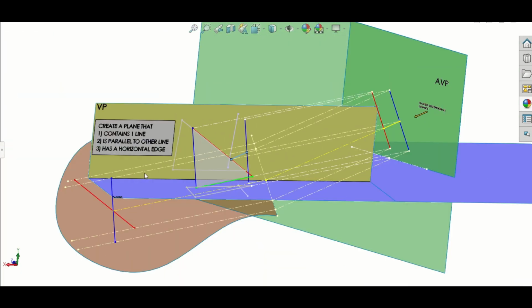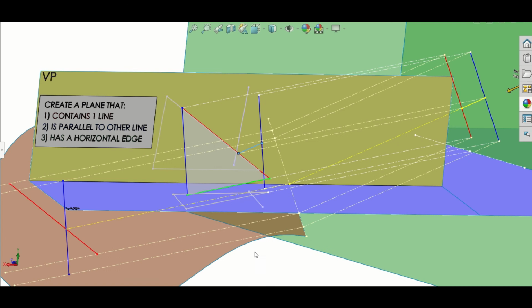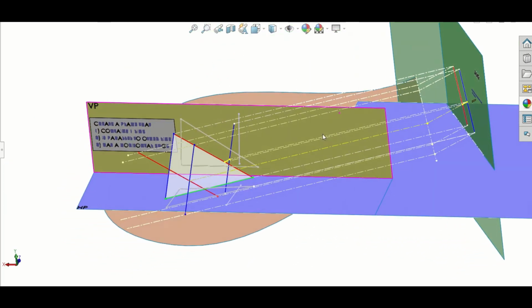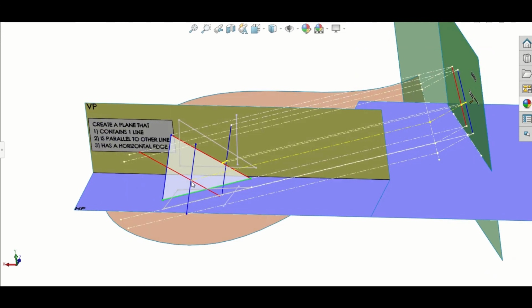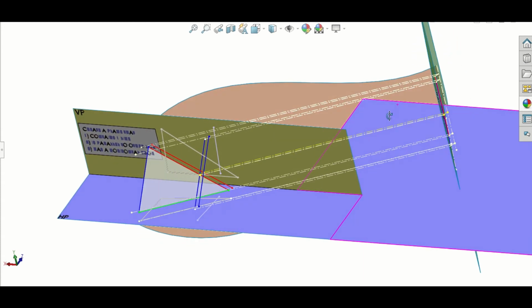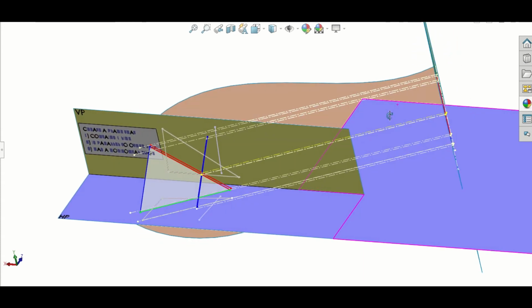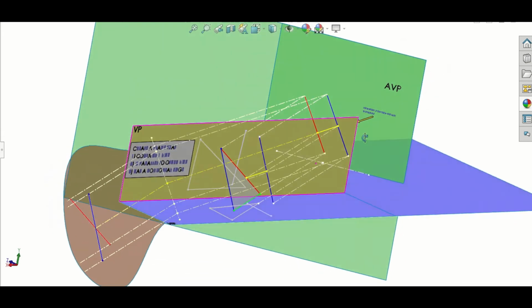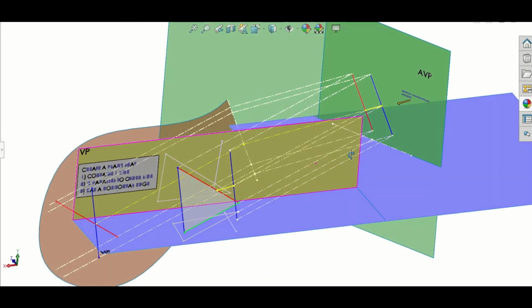Once I turn back again to look perfectly in at this view here, which was perpendicular to the lines, that yellow line becomes a point view. So just watch it once more now, and we'll get back to paper then. When I can see perpendicular to these two lines, my yellow line becomes this point view down here. So just keep an eye on it, and there, we're just about there. That is the shortest distance between two lines, or the shortest perpendicular distance between two lines, the first one.